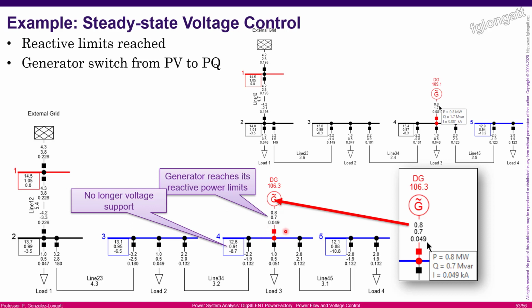But you must be careful about those limits because they have effects on the performance of your power system. As a consequence here, the voltage is no longer supported by this DG, and as you can see, the voltage drops. I hope that you will be able to see how important is the reactive power contribution of DG units inside the distribution system. They can help, of course, if they have enough capability of producing reactive power. Those new DG have possibilities of producing active power. We want active power because active power is mainly what we use inside homes. But keeping the lights on, keeping the distribution system working, we need more than just active power. We need also voltage support, and that can be done by